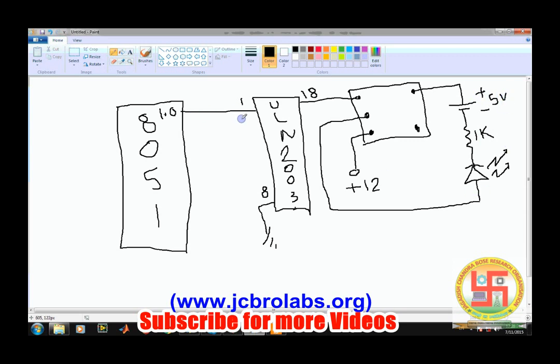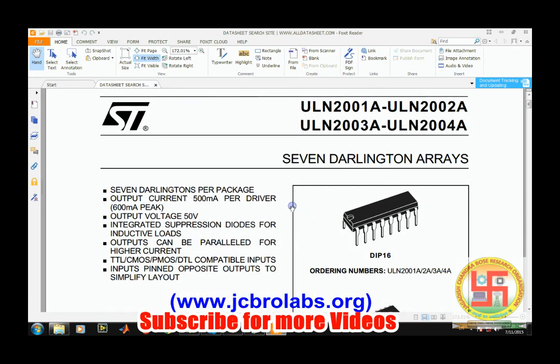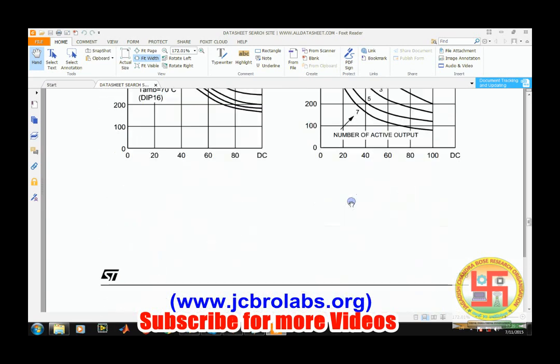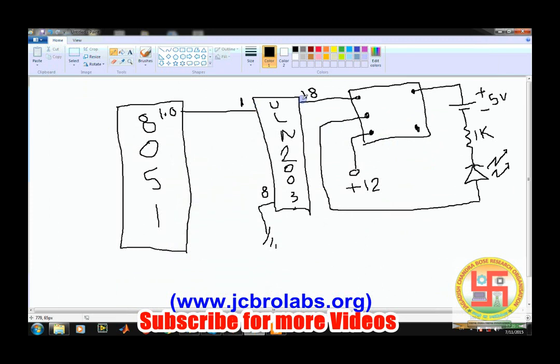So as soon as we apply 0 here, this relay will turn on, and just by sending 0 and 1 we can make this LED on or off. When we apply 1 here, we get 0 at the output because it is an active low output. So on applying 1 we get 0 at the output. Similarly, like this we can connect it. So now let's write a program for the same.